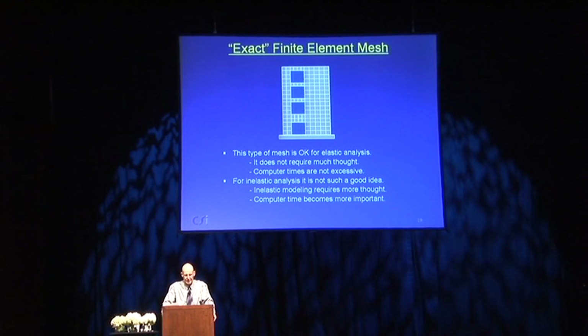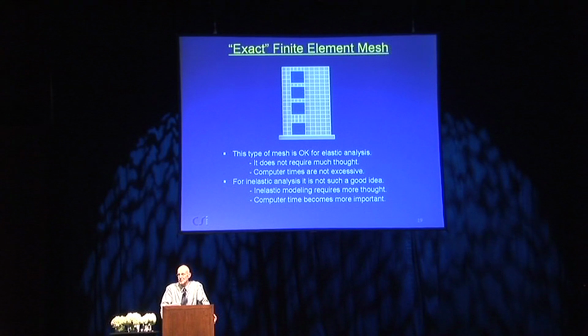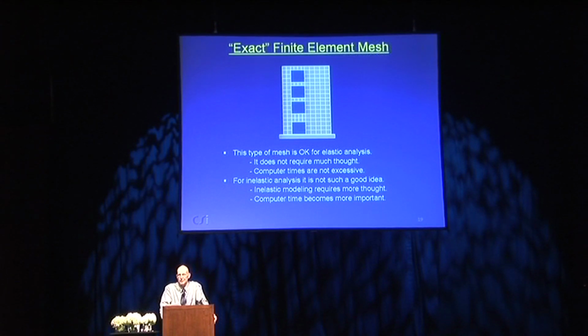And this type of mesh is fine for elastic analysis. It's not necessarily necessary, but it's okay. Firstly, it doesn't require much thought. And SAP, for example, has got very nice meshing capabilities that will do the job for you. You don't have to worry about it. And if you're doing a linear analysis, the computer times aren't very great, so it may be overkill, but it doesn't really matter very much.